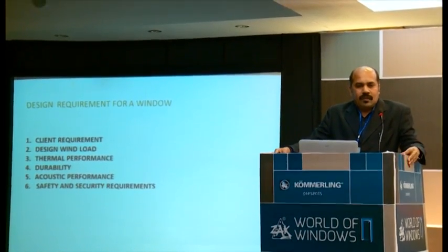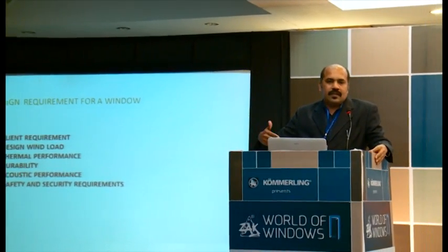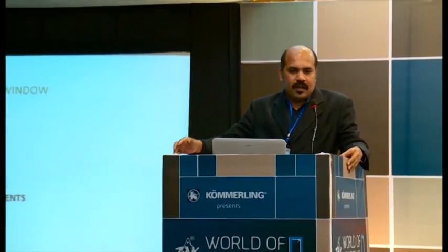You don't know, because right now the glass thicknesses, the thermal requirement like the U value, and whether the building requires acoustic performance, such as a metro running or an airport next to it, are not considered. You're selling a building to a resident, so these are all considerations you need before designing the building.